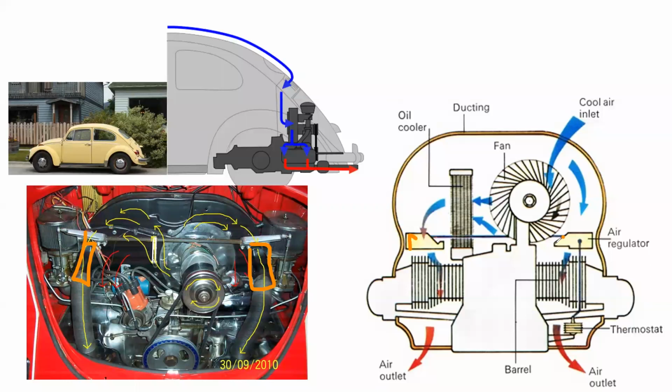At low temperatures, like cold temperatures, these valves will be fully closed, so air will not pass through the cylinder block itself. This is the cylinder block, located below this. You can see there's a small pan-like thing, and below that is this section. It measures the engine temperature and uses a thermostat valve which controls these doors here.